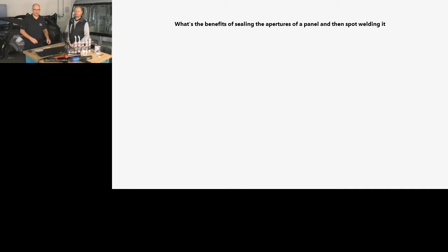We have other solutions to do that with an epoxy material when we bond panels together. But in this case, we have an increase of the structure stability, if we use a high strength material for this application. In this case, if we don't want to have this high strength, or the strength increase of the joint, then you can use the sealant in between to make a spot weld through. Okay, good. Hope this question is answered.